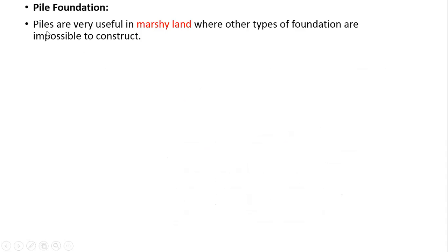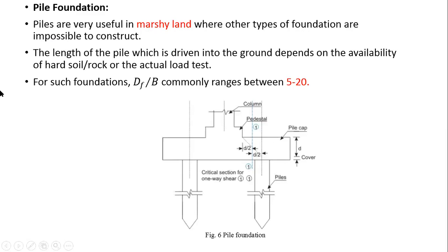Piles are very useful in marshy land, where we have very loose soil over the top. Always the land is submerged in water for a very long period of time. We call it daldal, marshy land, where other types of foundation are impossible to construct. So in that case, we have to provide a deep foundation like this.